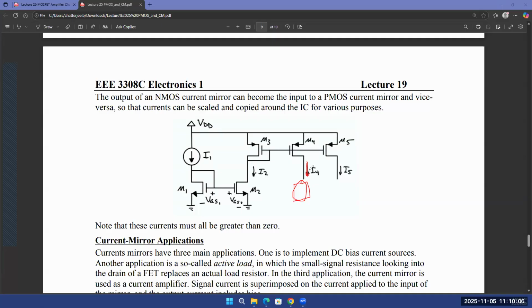If you want to do it, you can do it. It doesn't matter whatever circuit; you can connect any other circuit here. If you want to connect that gate to this gate, you can do it. I don't know what that will do to the circuit; you have to analyze and figure it out. But you can have 100 transistors here. You do not need to have one transistor. That's why I have drawn a black box. What we are ensuring is that the current going into that black box is forced. The current is equal to I1. I don't care what that black box has. All I wanted to know is whether I can copy this I1 current 100 times, and I am able to do that through this.